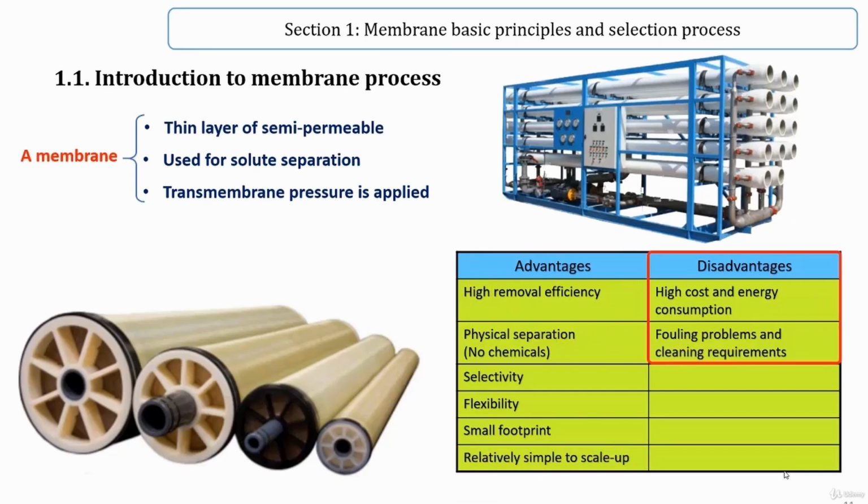As main disadvantages of the membrane, high cost, energy consumption and fouling problems are presented. Cost is one of the major barriers in membrane technology. Higher energy consumption than the traditional granular filtration. Capital cost, installation, maintenance, and membrane replacement or defouling are also expensive.